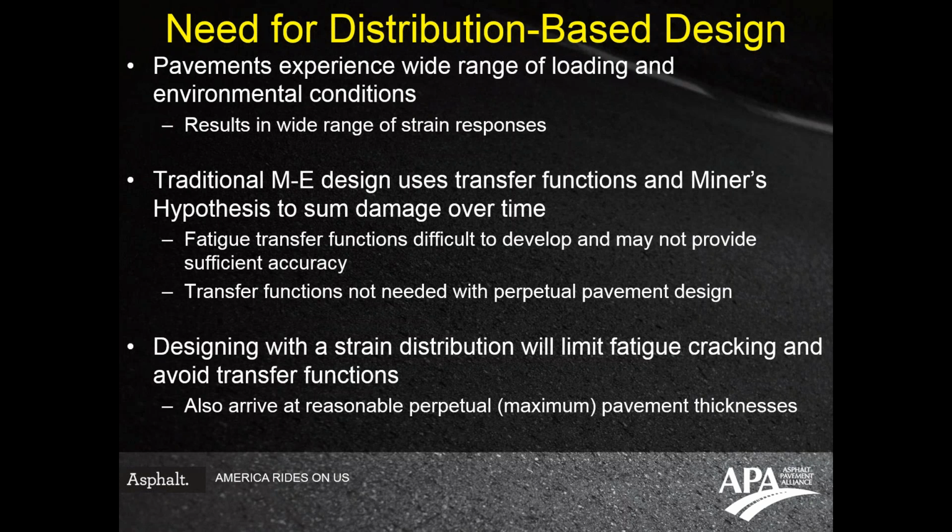And that's the third point on the slide there. Designing with a strain distribution will limit fatigue cracking, will limit rutting, and help us to avoid transfer functions. And as I'll show, it will also help us arrive at reasonable perpetual or maximum pavement thicknesses.